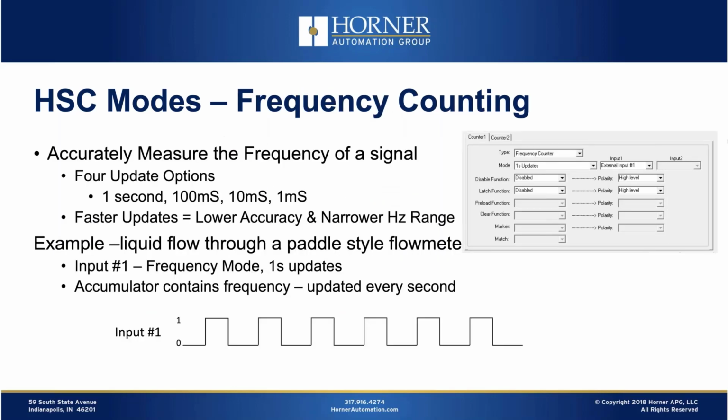All right, now let's move to some simpler applications or simpler setups. Let's talk about frequency counting. With frequency counting, instead of selecting totalizer as your type, you effectively select frequency counter. Once again, the Cscape snapshot is on the right there.